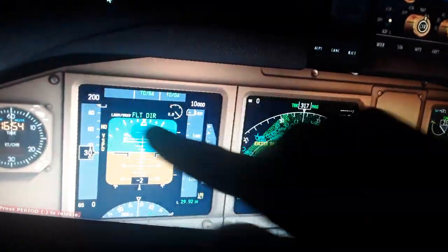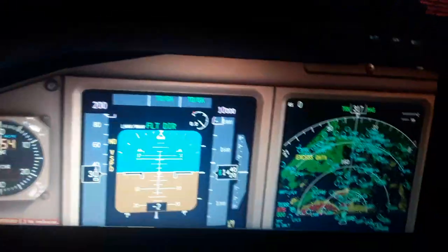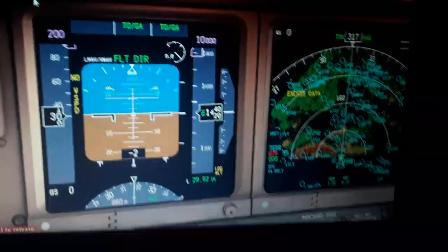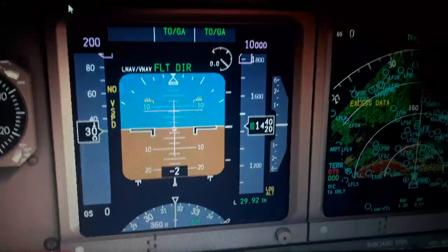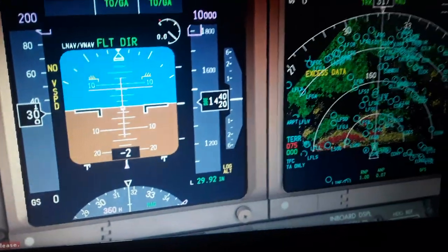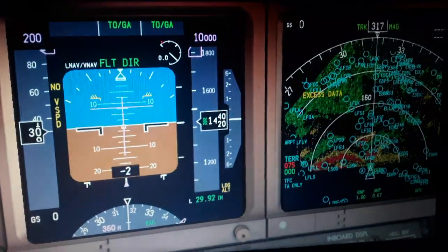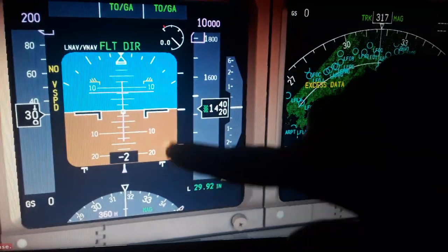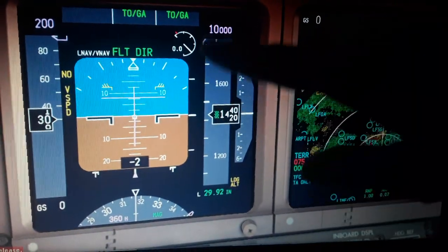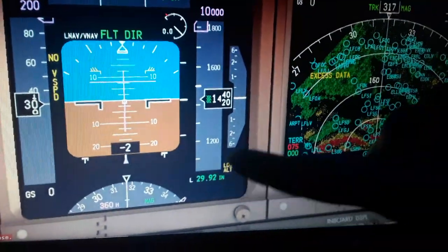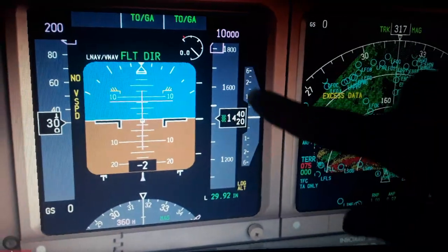the primary flight display. You can see the airspeed indicator, the airspeed selected from the autopilot and flight director system panel, the ground speed. So this is the airspeed page. We have also the radio altitude above the ground level, the magnetic heading or track, the magnetic north pole and true north pole, the magnetic variation depending on where we are in the world. We have also the barometric altitude above the sea level, the target altitude, the rate of climb or descent of the aircraft in tens, hundreds and thousands of feet per minute.